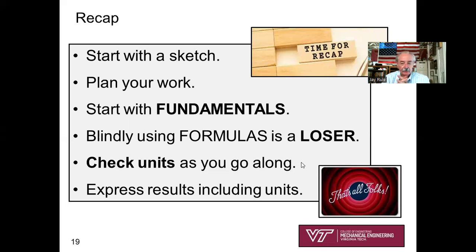I was careful to get my power units from megawatts into kilowatts, kilojoules per second. And I had to be careful to get my kinetic energy terms in kilojoules per kilogram, not meter squared per second squared. You saw that at the end of my work, where I was clearly stating my results, I expressed my results including units, not just numerical values.